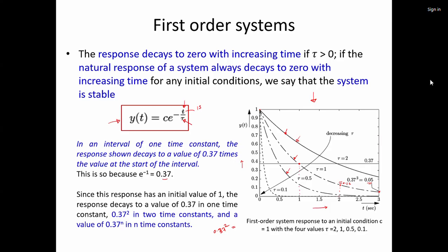As the temperature is changing, if the time constant of your probe is smaller and smaller, it will detect very quickly. But if you use a system which has a long time constant, even if the change is happening, you may not be able to detect it. If the temperature is going from 50 degrees to 52 degrees and going to 43 degrees, 56 degrees every second, and the time constant of the system is, let's say, 1 minute, you are not able to detect anything.